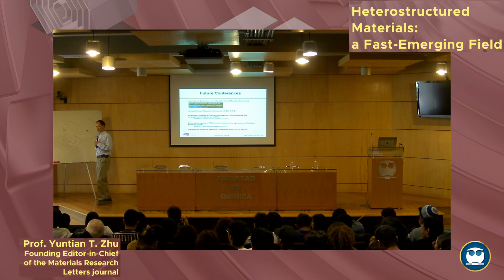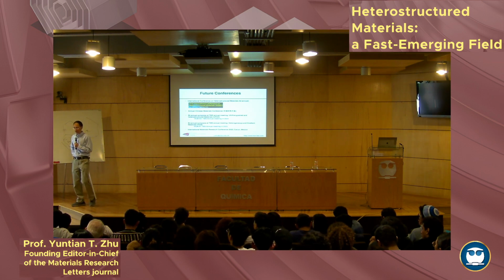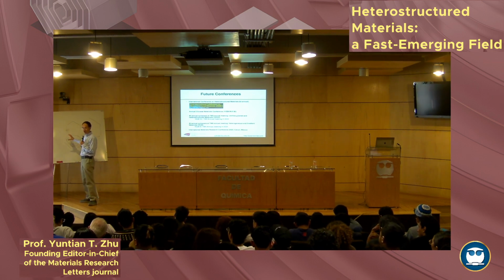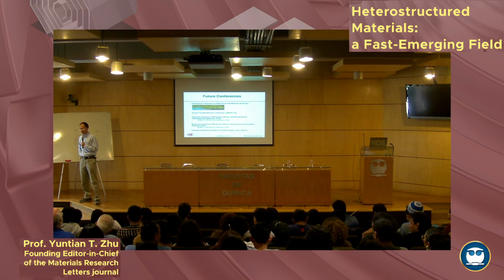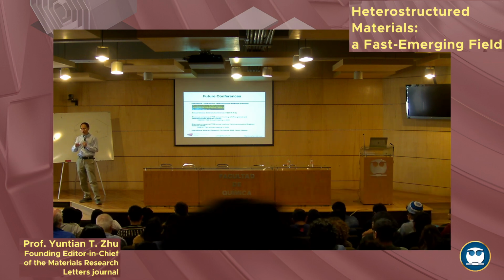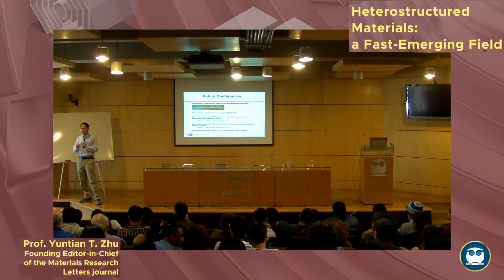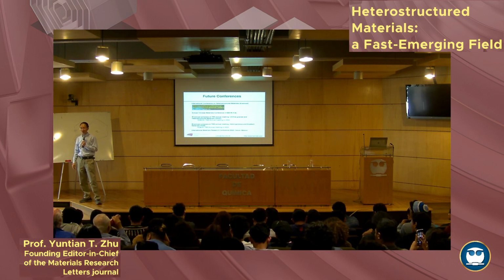I don't get exactly your question. I think you have designed for more dislocation pileup. So that's a design. From alloy design, you want the alloy to have low stacking fault energy. Otherwise, dislocations will cross-slip easily and do not like to pile up. So planar slip is desired.